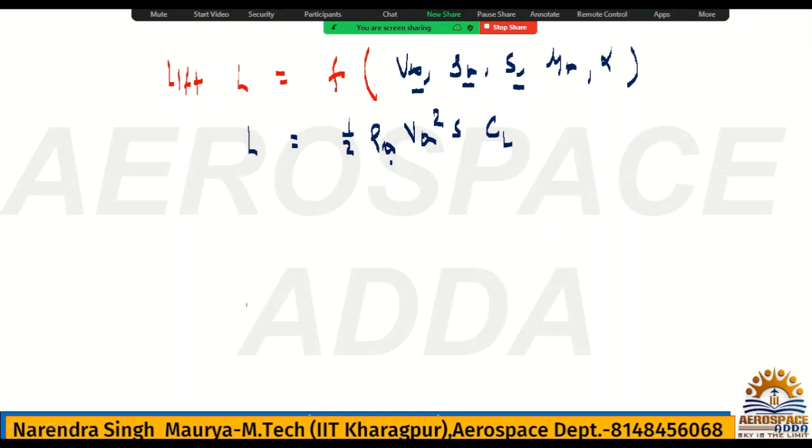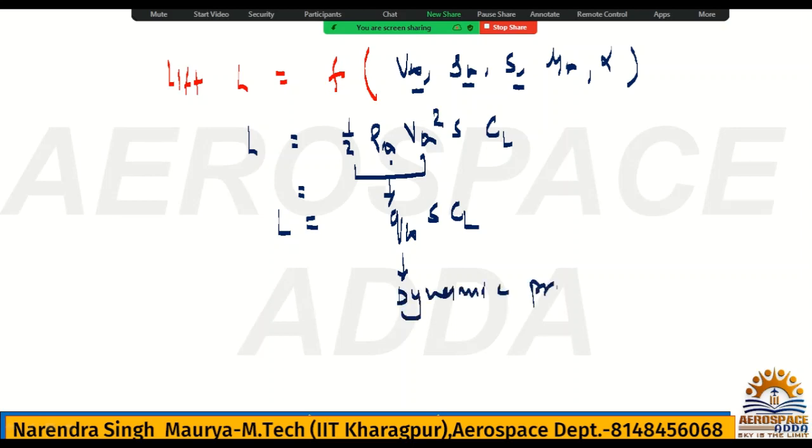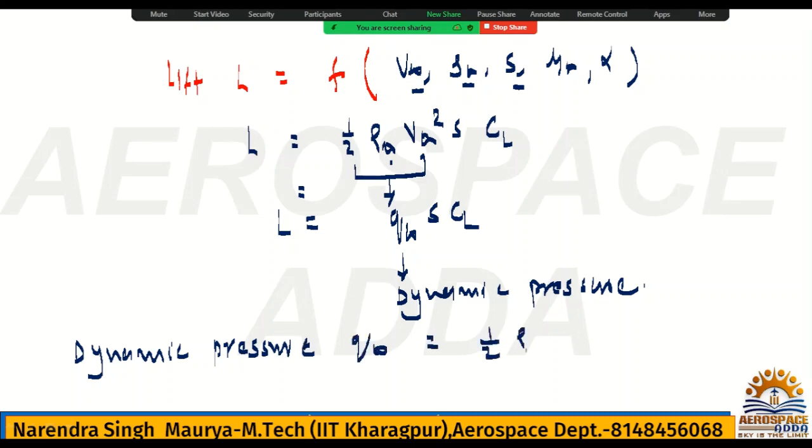Okay, so now here this part is sometimes called Q infinity, okay, S into CL, which is nothing but lift. What is the Q infinity? It is nothing but dynamic pressure, okay. So what is the dynamic pressure? You all know, Q infinity. What is that? Half rho infinity V infinity square.